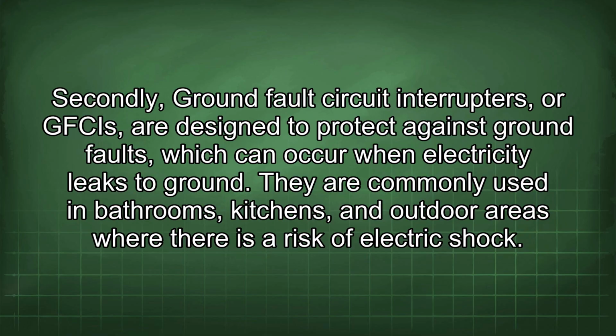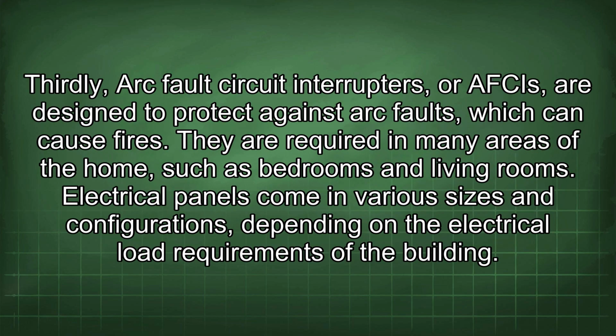They are commonly used in bathrooms, kitchens, and outdoor areas where there is a risk of electric shock. Thirdly, arc fault circuit interrupters, or AFCIs, are designed to protect against arc faults, which can cause fires. They are required in many areas of the home, such as bedrooms and living rooms.